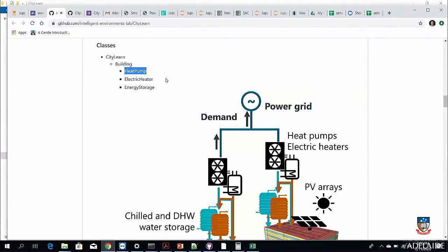The efficiency of the heat pump is given by the coefficient of performance, or COP. For cooling, the COP will be better if the outdoor temperature is colder than the indoor temperature. The coefficient of performance is how many units of cooling energy we can obtain per unit of electricity, or kilowatt. Typically we are in a range of 2 to 4, which means that for every kilowatt of electricity we are obtaining 3 or 4 kilowatts of cooling energy. But this is influenced by the outdoor temperature. The lower it is, the higher our efficiency, but the less cooling we need because it's colder outside.